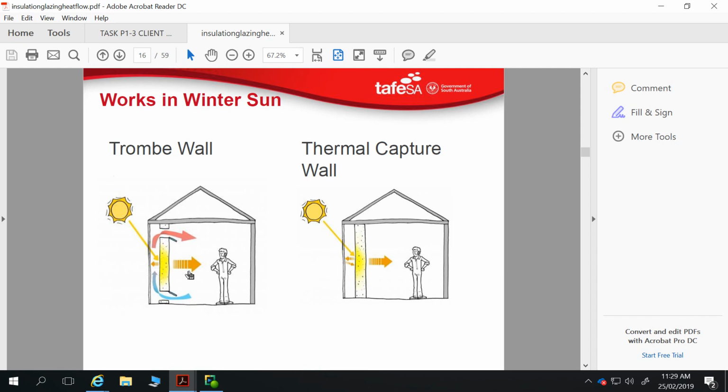How close is the wall to the actual windows itself? With the gap and everything, especially on the right hand side where it's fully enclosed, that would be a fire risk. A fire risk? Yeah. Because if the fire would burn through that glass, in between two bits of glass, you've got a giant pot of air causing a chimney backdraft, and you've got another whole section of air ready to go for another backdraft straight away, if you had a fully enclosed one.